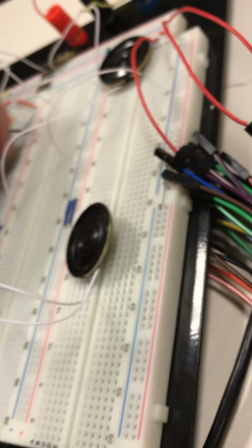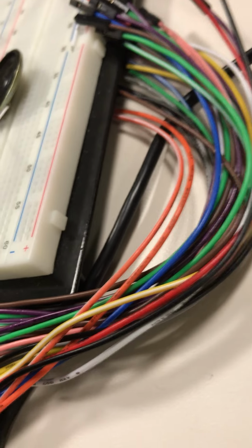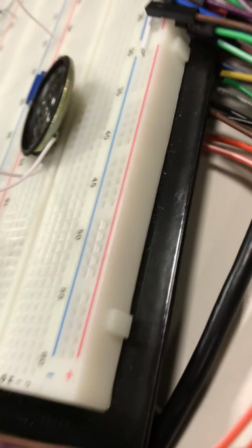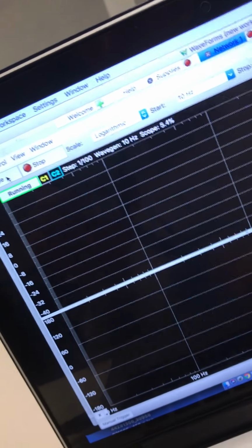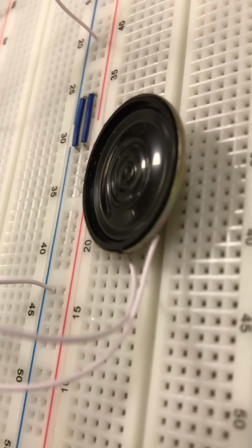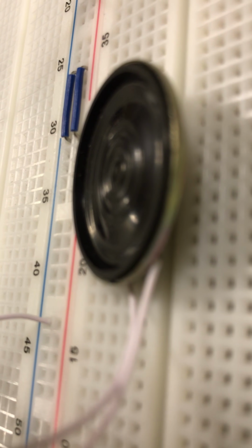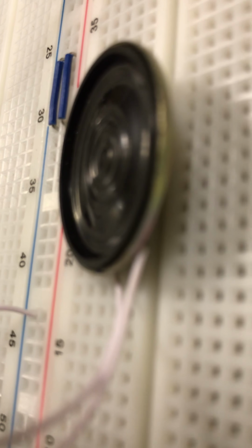Good. And then the last one we're going to run is the high pass filter. This one should not work at low frequencies and will only work at high frequencies. We're starting it now. You can see you cannot hear it yet, but once we reach the 3 dB cutoff point, you should be able to hear it. Perfect. And you can hear how once we got to those high frequencies, we were finally able to hear the sound.